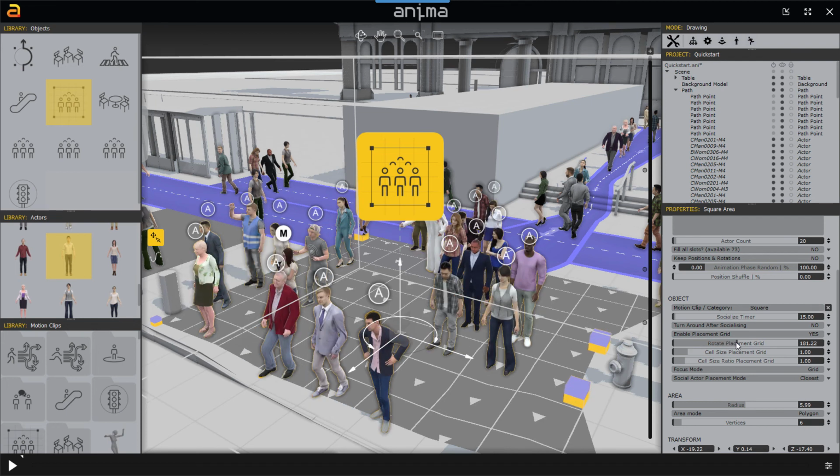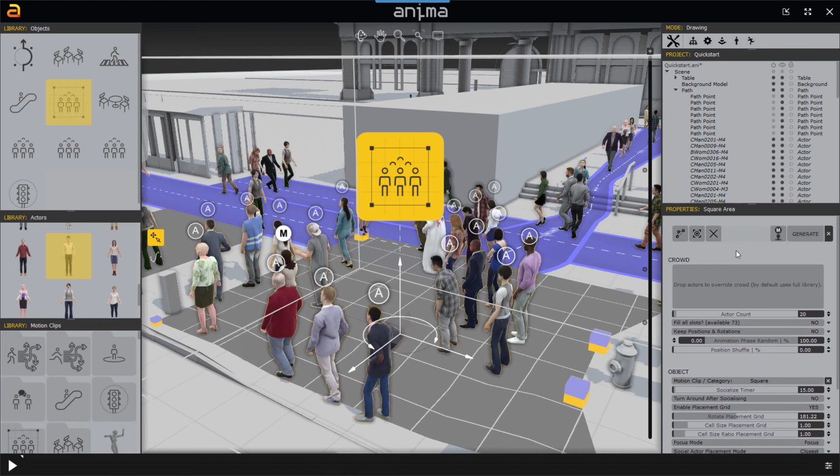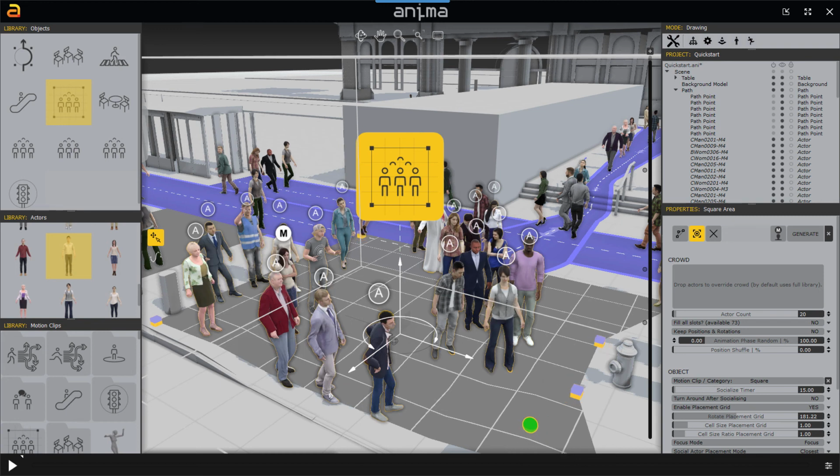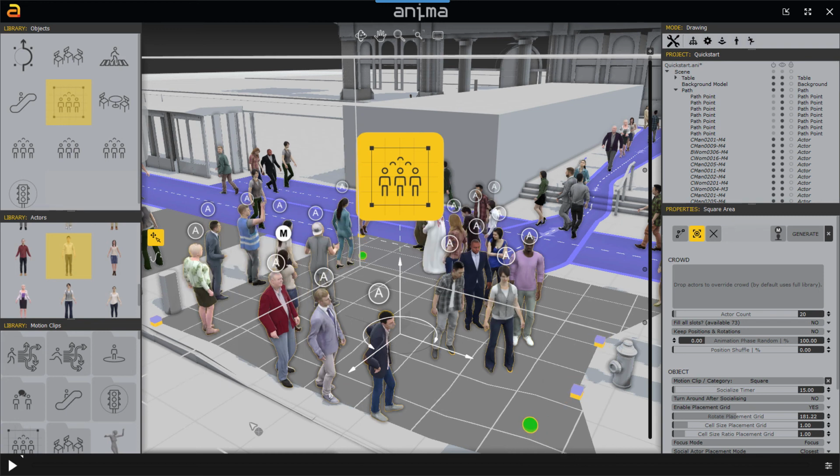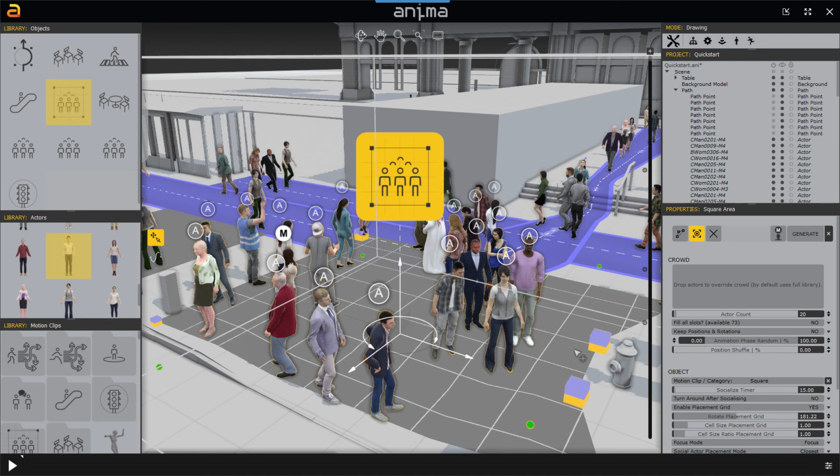If you'd like the characters to face in multiple specific directions, then you can use focal points. To do this, set focus mode to focus, and just like before, use the Add Object Point tool and click anywhere in the 3D viewport to add a look-at target. Keep clicking to add additional points, and right-click or deselect the tool to exit creation mode. If there are multiple points, characters will rotate to face the point that's nearest to them.